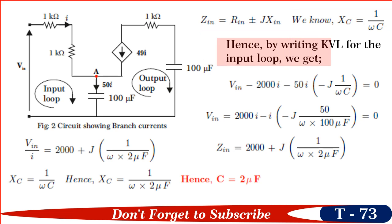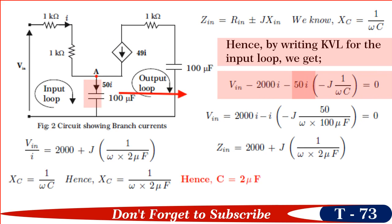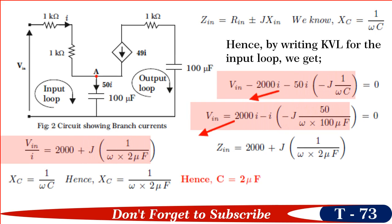Now, by writing KVL for the input loop, we get Vin minus 2000I minus 50I minus j1 upon omega C is equal to 0. Or by solving and substituting the values, we get Vin divided by I is equal to 2000 plus j into bracket 1 upon omega into 2 microfarads.